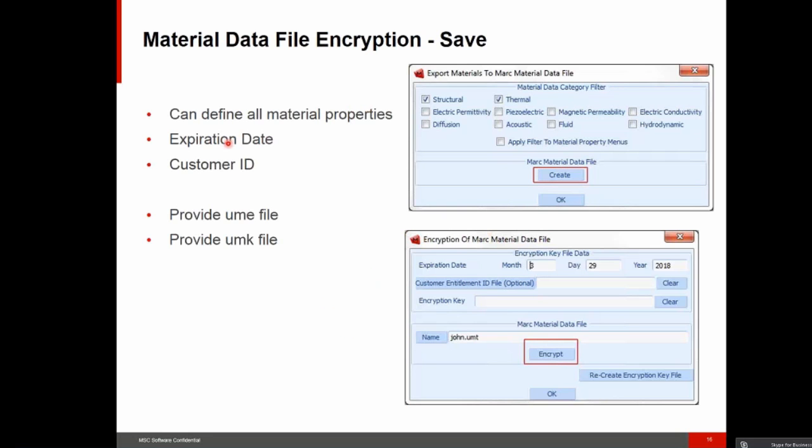So it's not only work that we did in material characterization in terms of material data fitting, we've also done some work in terms of utilizing your material input, and you can put it in a particular file. You can save all your material, your isotropic or your Mooney, all your tables, whether or not they're temperature-dependent tables, and you can place them into a file. You can basically have multi-physics representation of the material behavior in that file.